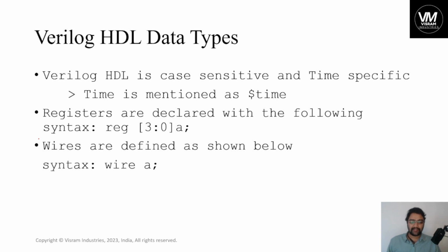So, a set of commands. Registers are declared with the following syntax: reg, then the size in bits, what size the register is. Here a register is not only a memory element, but any device that we are describing in this way. Outputs are also called registers and inputs are always called wires. Wires are nothing but interconnects.